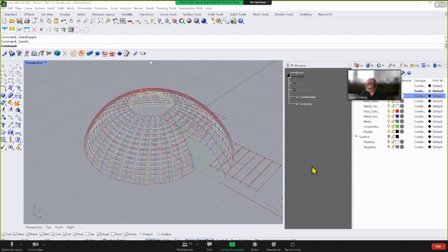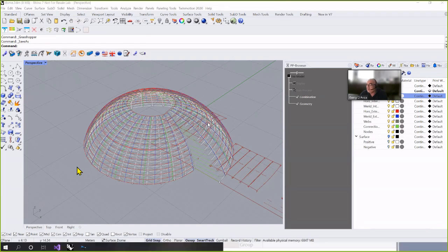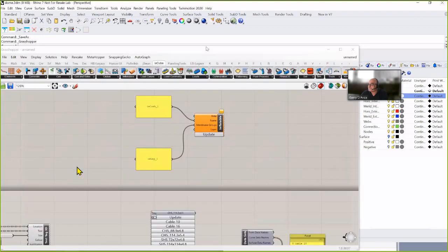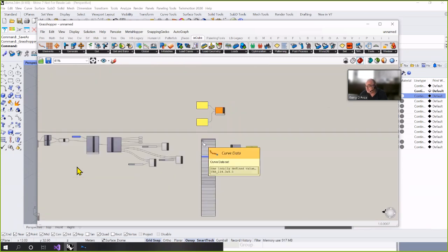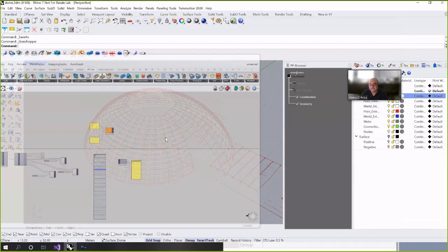Well, the concept today was to show you about this falko. I don't know how many of you out there are using Rhino and Grasshopper. I know there are some powerful power users. Somebody asked me to do ETFE cushion patterning for thousands of cushions. How can you make thousands of cushions manually? It's impossible. So using this tool, you're able to generate thousands of patterns in half an hour. That's a huge amount of time and a huge amount of money if you think about it.